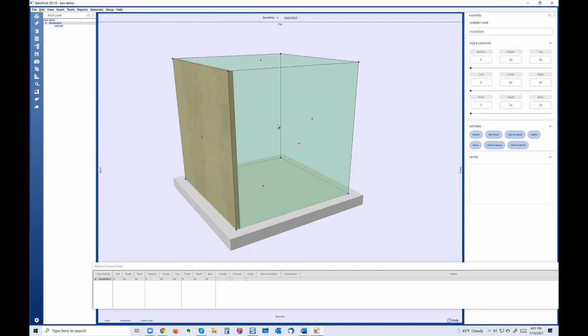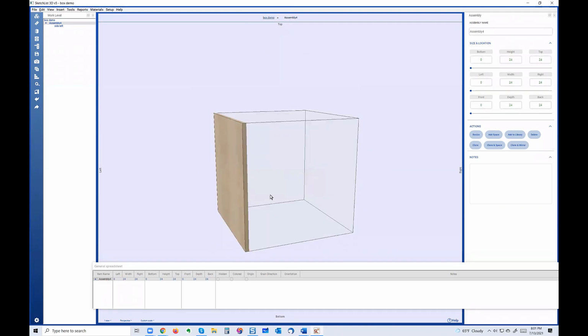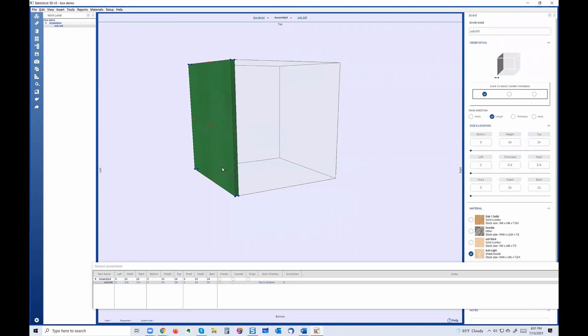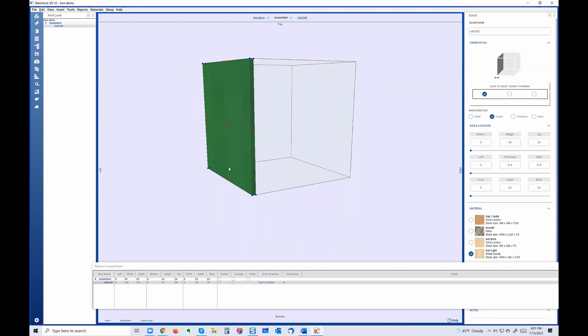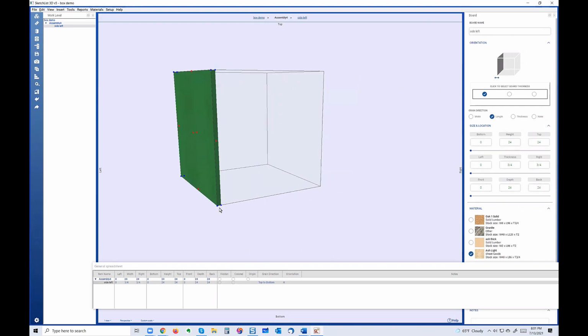Okay. So now I've jumped back up. Oh, I was in project level, but now I need to go to assembly level. So I inserted and I sized, and I want to locate. So I'm going to take that blue dot and right click it and put it 2 inches from the left. Right click the blue dot. Blue dots locate left, and I'm going to say okay.